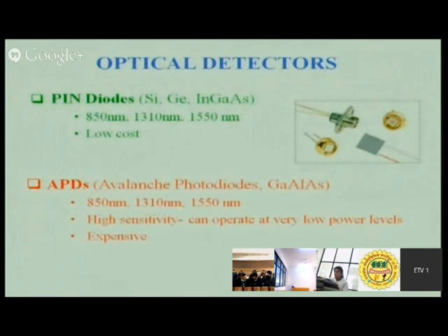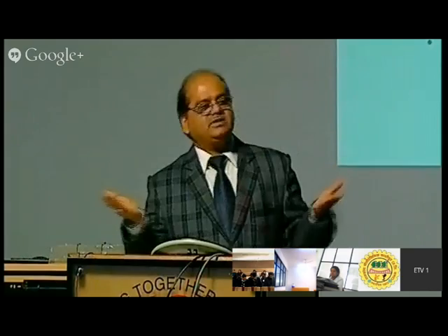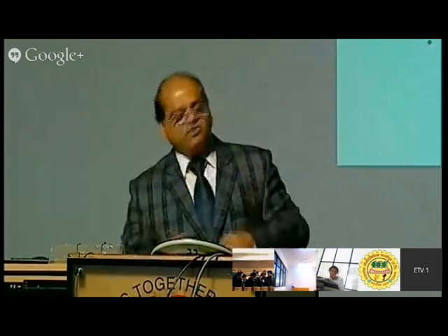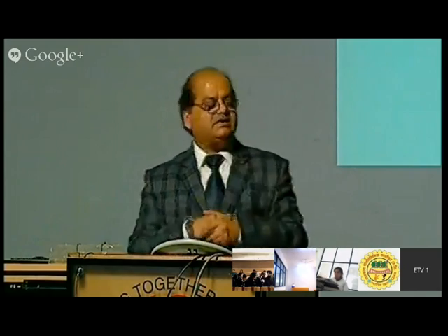So one has to decide. The best combination is laser and APDs for single mode fiber, or we can have the low cost components, LED and pin diode. It depends upon the service provider, or upon what type of quality is required for a system. Then I will cover the advantages of optical fiber.